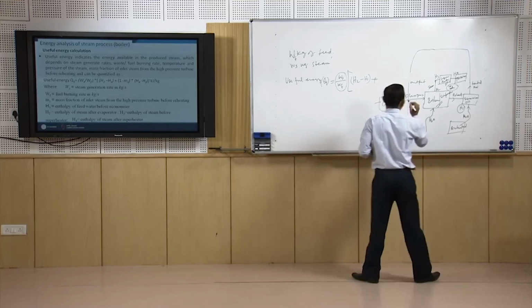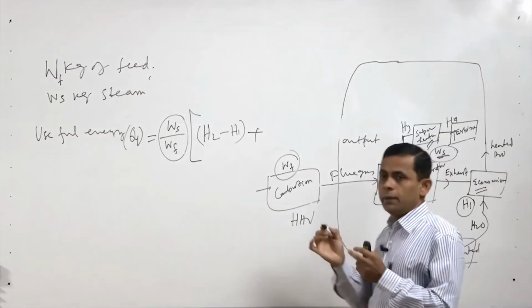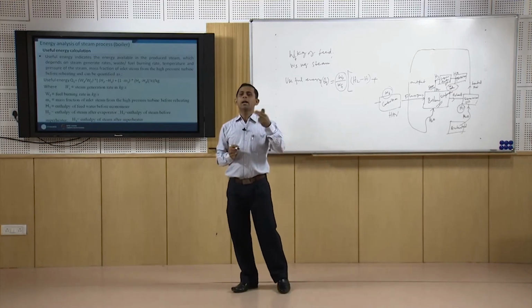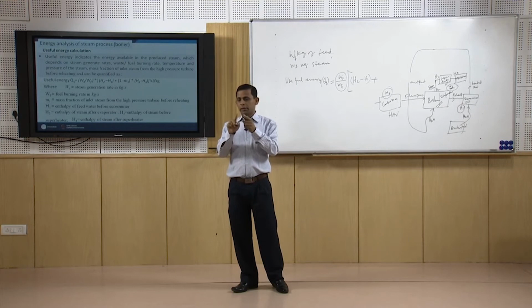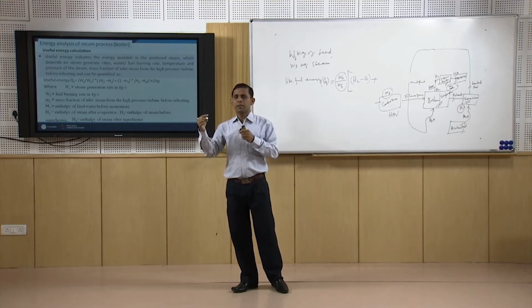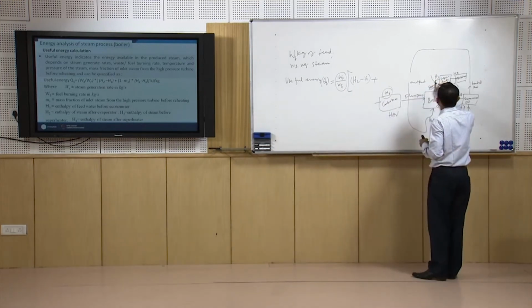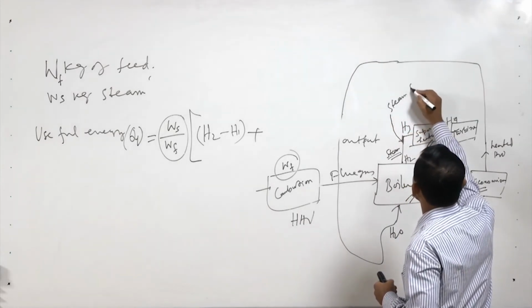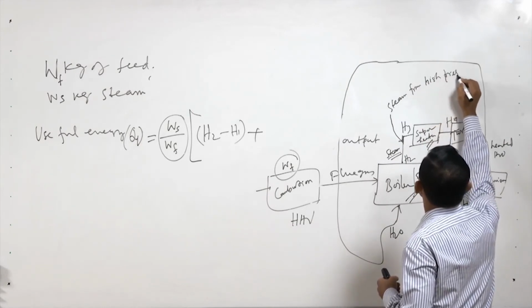plus, here one interesting point is that we are producing saturated steam. If in our plant you have a number of turbines, one turbine will be at higher pressure. Higher pressure steam will exit from the turbine after use, and it will have lower pressure. It may be possible that if the downstream turbine is using lower pressure, the exit from the first turbine can be used here. The steam exit from the first high pressure turbine can be used here. So, steam from the high pressure turbine.